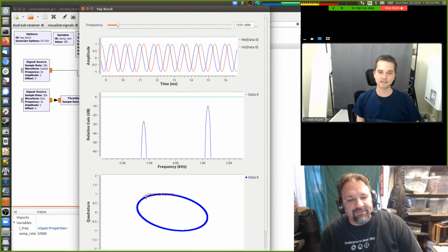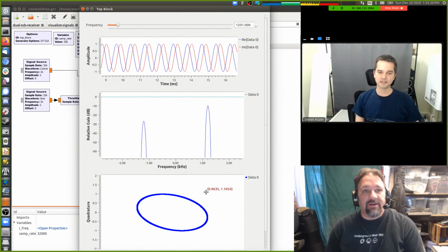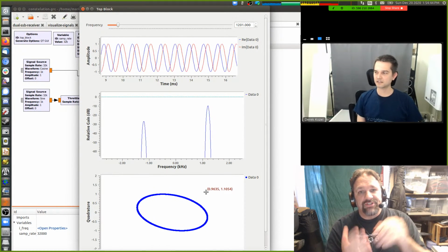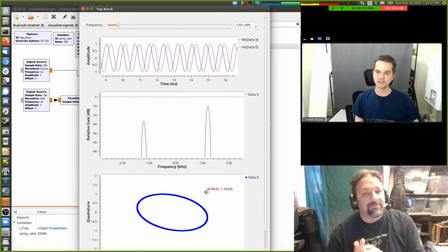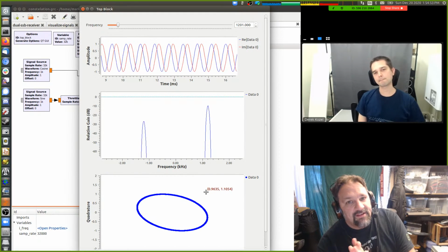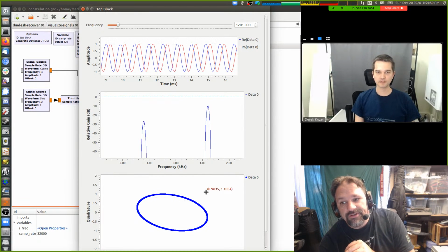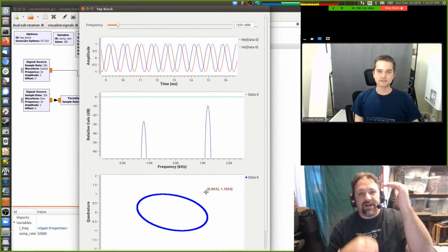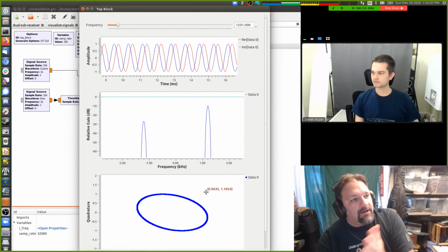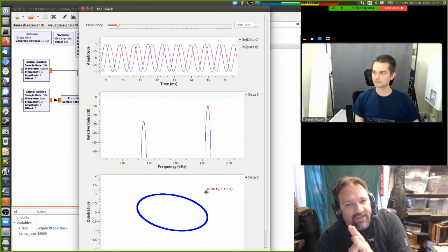Your constellation graph down here, you get 4 little boxes of signal, and you've got a literal sum of two sine waves that are 90 degrees out of phase, and you just transition from one amplitude to another on those sine waves, and your dot moves around that constellation graph. I get that instinctively. I understand BPSK and QPSK, and even QAM64. You just have more amplitudes than just positive and negative, and you're able to look at it on that IQ graph and decode that. I still haven't figured out how sideband works in that.